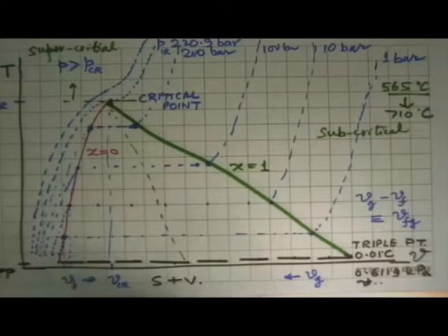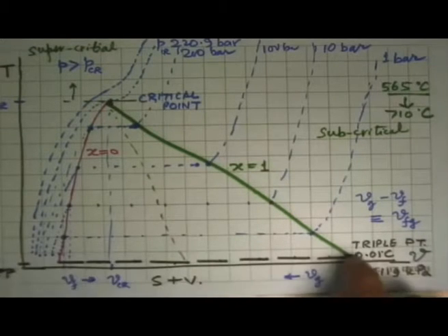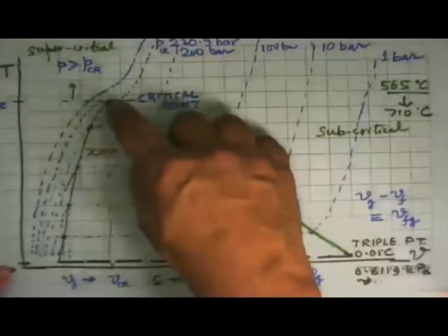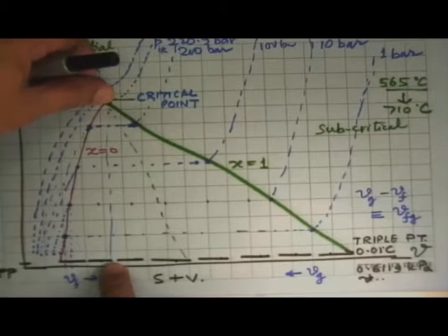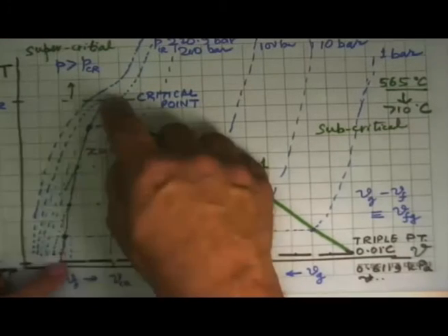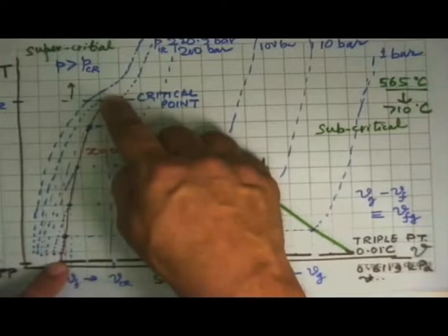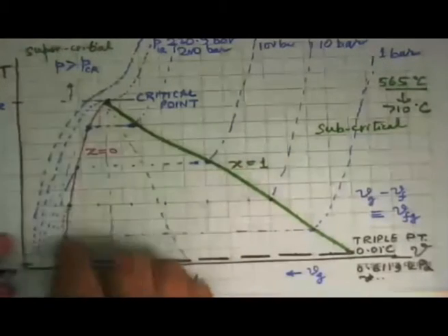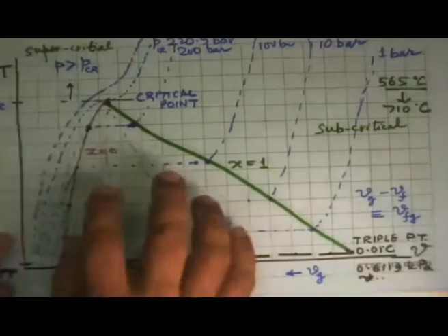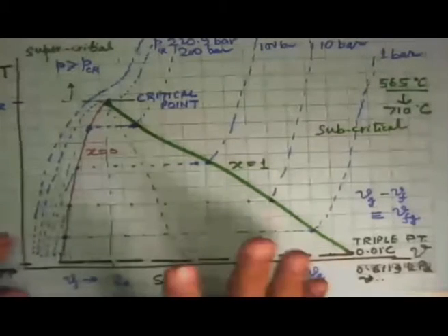Okay, so this is one thing that comes up, that there is a limit at the bottom, the triple point, at the upper, a critical point. If temperatures are between these two values and pressures are between the corresponding triple point and critical point pressures, only those conditions we can expect to see a wet saturated state.